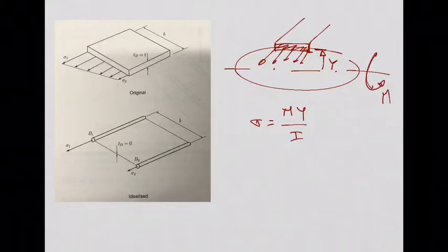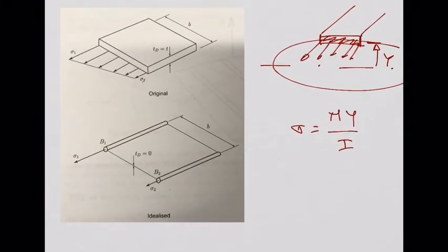Don't forget, we are trying to find the area of these booms that you see here. I'm going to build an idealized model where I'm going to have one boom, this one, boom 1, and boom 2. Okay? As you can see, I'm going to assume 0 thickness for my skin. And I have this idealized model, for this plate element, with 2 booms, B1 and B2.